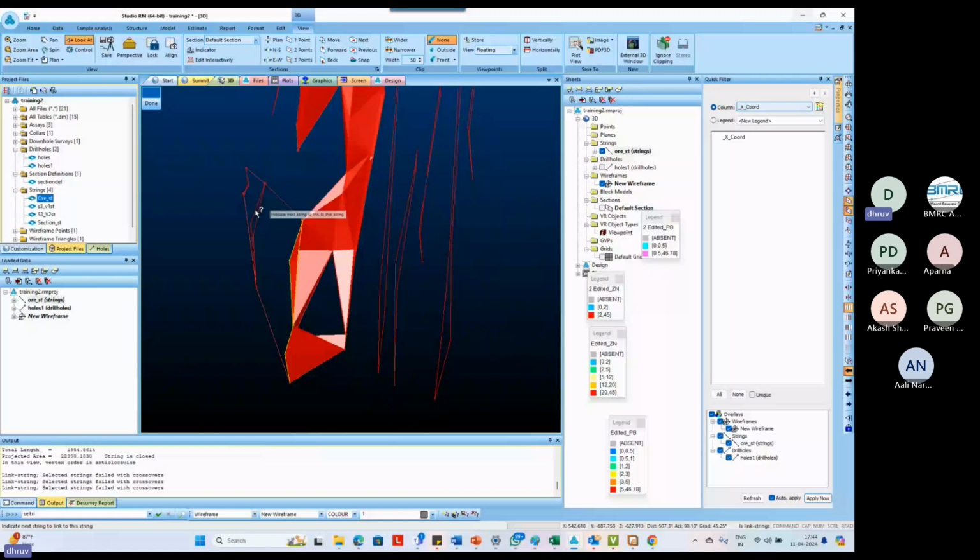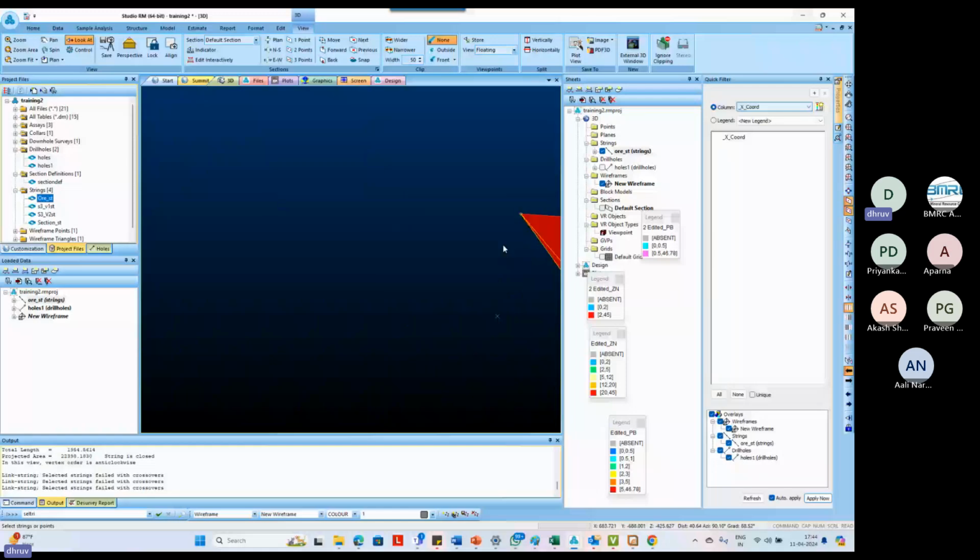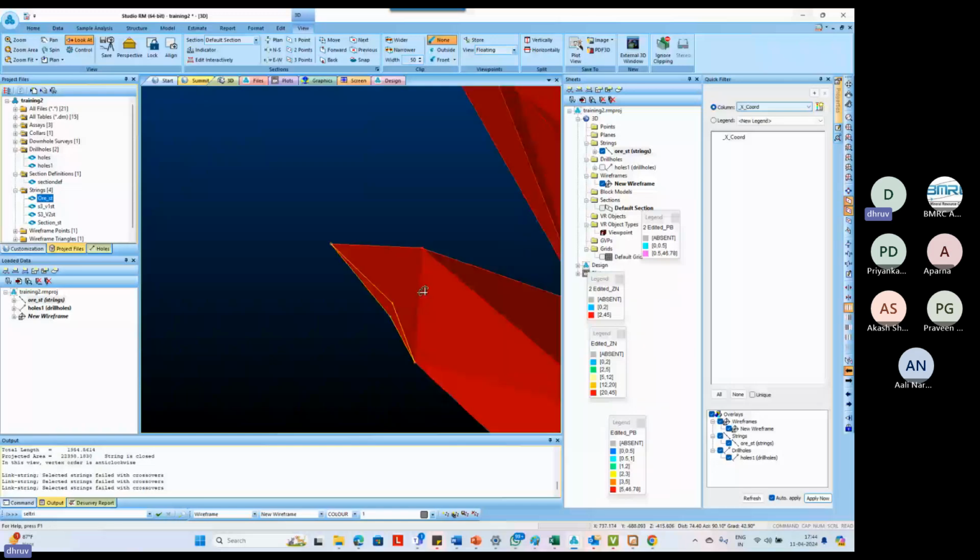Okay. Now to end a link boundary, to close a linking. Right now, if you see here, this is open-ended, and this is the last string. So you have to close it. For ending, the command is ELI, end link boundary. So it is now closed. Okay.